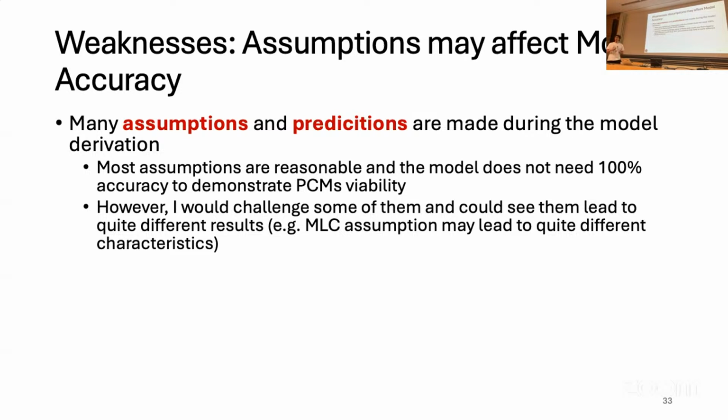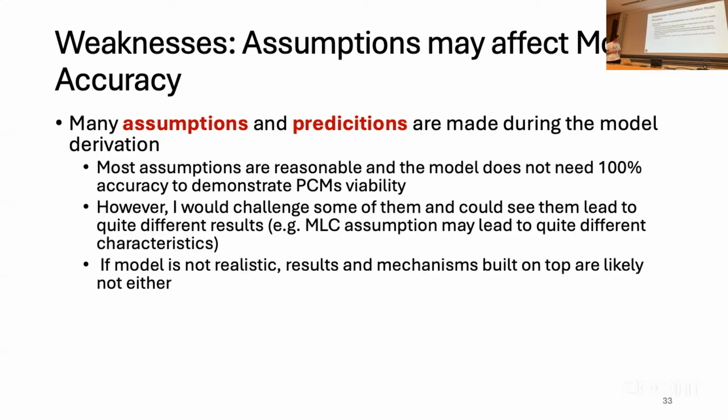In the paper, there's the implicit assumption that this does not affect the PCM characteristics like latency, energy, and endurance, right? But in my opinion, changing from 1 bit to 2 bits per cell will most likely increase latency and also energy for a few reasons. If you're interested, I can go into more detail later, but let's move on for now.